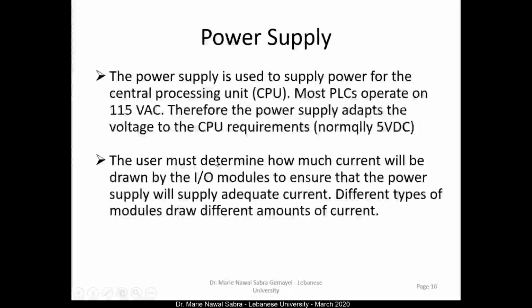The user also must determine how much current will be drawn from the input-output modules to ensure that the power supply will supply enough current for all of them. If not, we have to reduce the power that is outputted from the output modules by adding external relays.